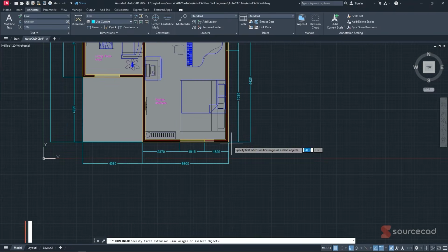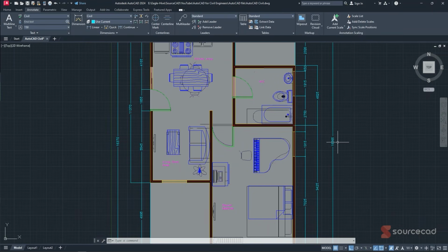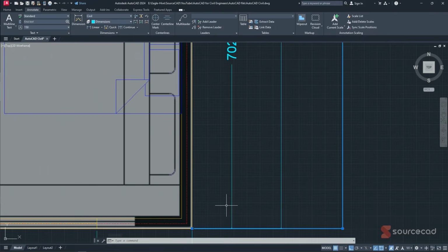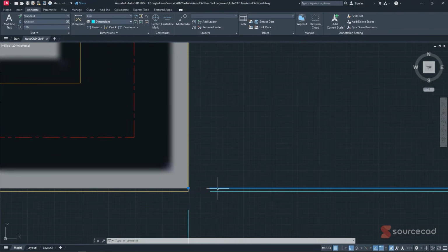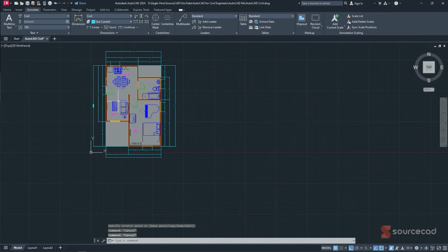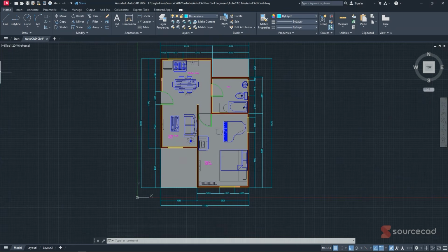After that, we're going to do a very simple check. Whatever we have on this side, which is 11190, we have to have it on this other side. Whatever we have on this side, we have to have it on this other side. So if it doesn't match, it means there's a hitch. We can zoom in and see at what point we have not clicked exactly. So over here, clearly. Once you click from this point to this point, let's confirm. Yes, 16370, 16370. And that's the way we simply create our dimensions.